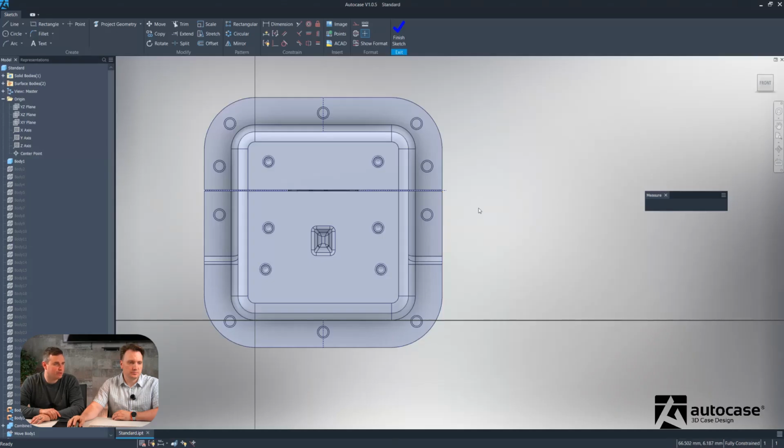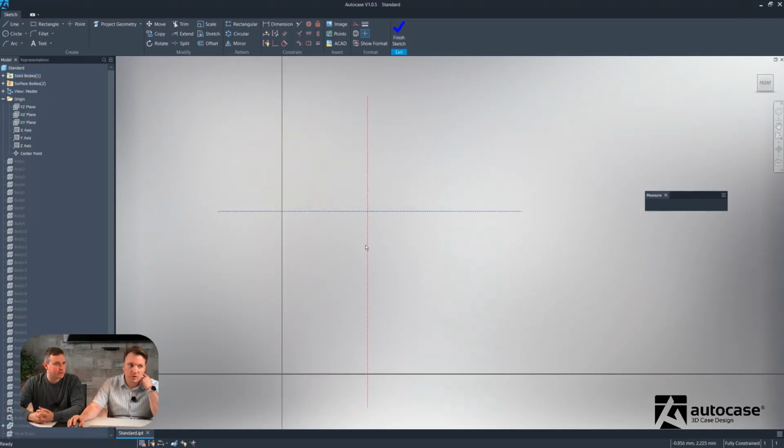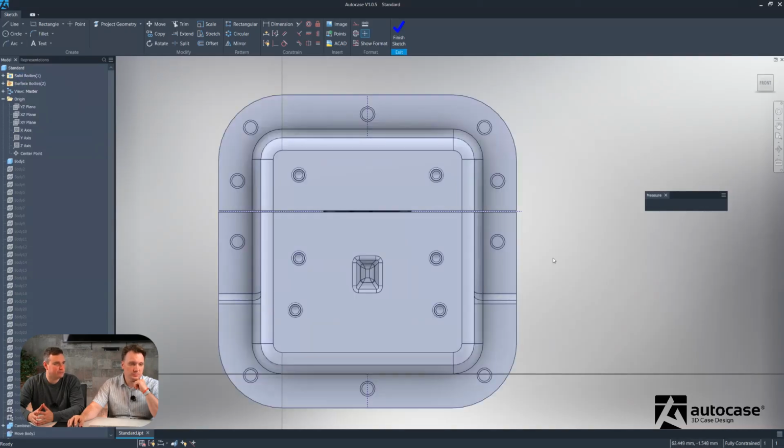Now, to be sure that we haven't missed any of those extra lines at this point, you can essentially hide the 3D body of the latch by going down to the visibility setting and seeing there. Yeah, so at this point you can see that we've definitely captured and deleted all of the extra bits of geometry that have been created, and we've just got our construction lines, so we can now turn the body visibility back on. So at this point, we've got some locked construction lines that we can use for measurement referencing.